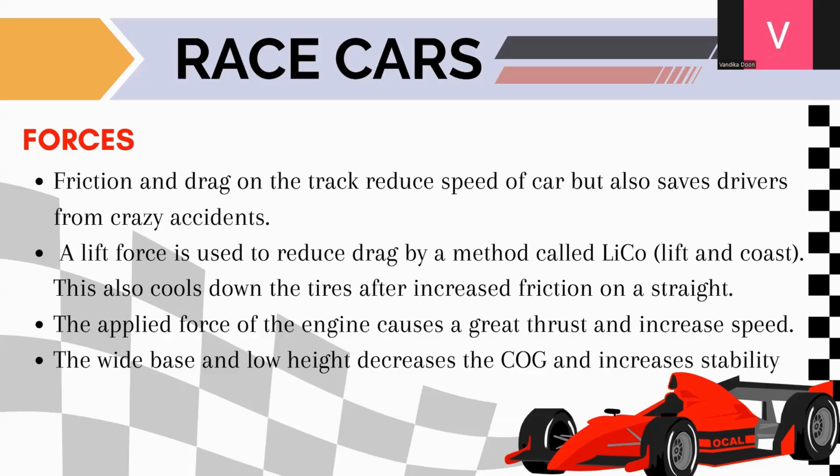And something that also acts on the Formula One car is the lift force. Also, they use a method called LICO. I saw this in the McLaren driver, Lando Norris. He was explaining it, and I was like, okay, I'm going to include this in the presentation. So, LICO, lift and coast, is a method used to reduce drag.